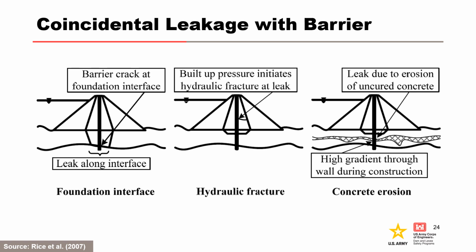Similarly, the coincidence of a crack in the seepage barrier and a seepage pathway may occur where barrier cracking occurs at the interface between rock types with different stiffnesses, where bedrock jointing also often occurs.